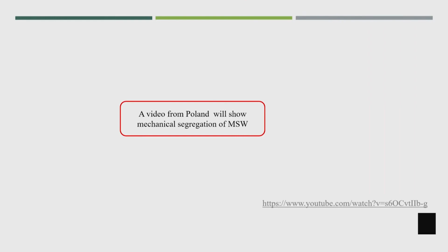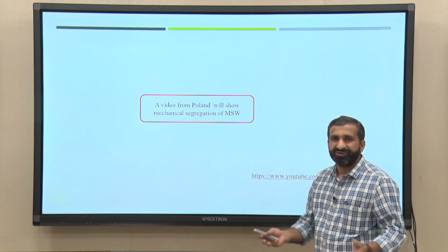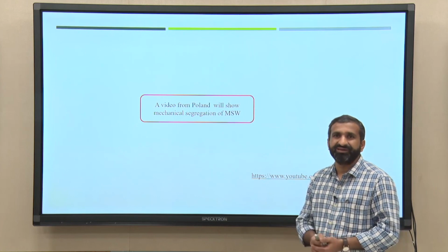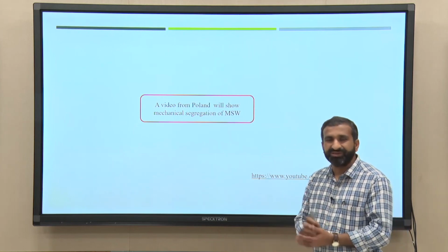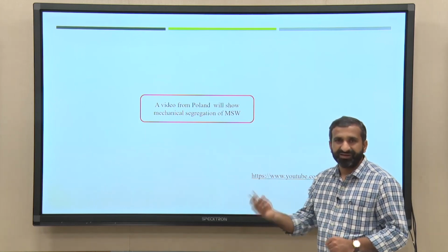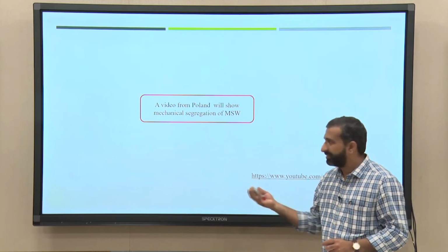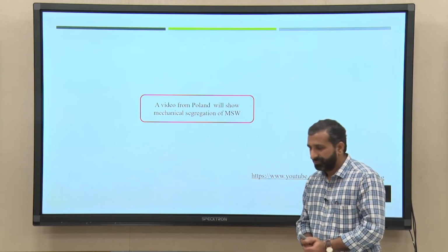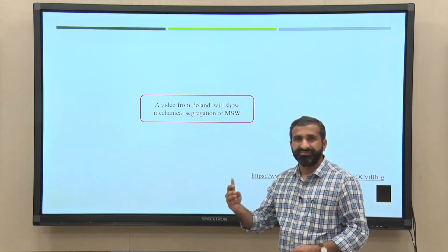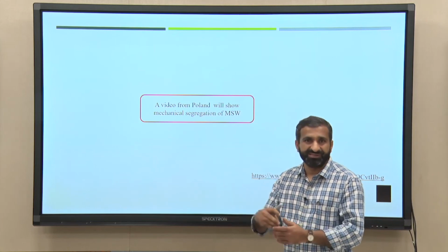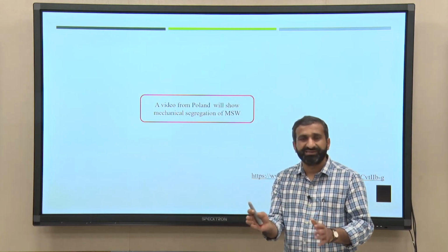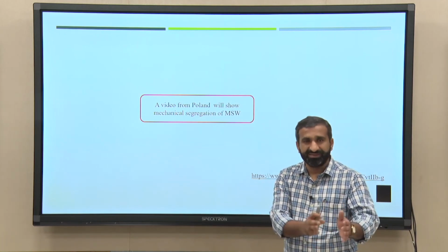So, by that we can understand the mechanical process is somewhat costly. Still, in a few cities in India these kinds of units are available, but not all the units together, and it is again based on the objective, especially if you target plastic. So, this kind of mechanical separation is very beneficial. Once segregation is over, the entire waste will go to the MRF station, material recovery facility. It is also possible that at the MRF station, these unit operations are available in the same area.